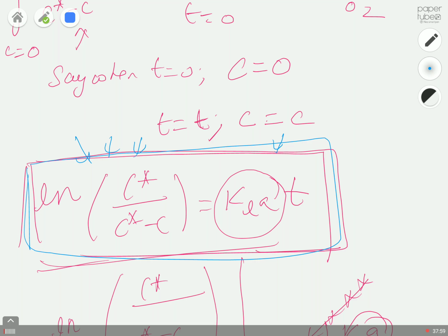So that's why normally we add an agitation unit. We increase the gas supply into the reactor, which means you can pass more gas per unit volume of reactor. That's why they increase the flow rate of air which goes into the reactor, just to speed up the transfer of O2 from the gas phase to the liquid phase. So these are the basic things you should remember.